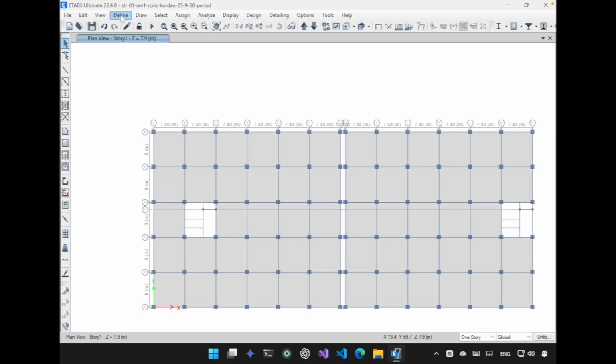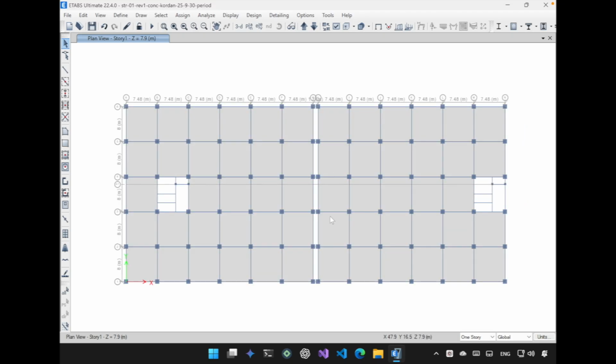For the 2800 code in Iran, we used this user coefficient based approach. So we've already defined C and K for this project, and now the program can calculate the earthquake forces for each story. If we want to check these forces and extract them from the program, for example, to evaluate overturning moments, one way is to graphically review the diaphragm forces.